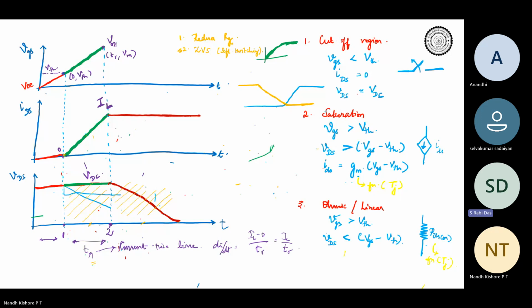But if you want to operate at high frequencies, you have to go for ZVS. You understand, right? Because you have to decrease your overlap time. If you want very basic reference materials, there are a lot of materials available online on the basics of ZVS and how people do it.